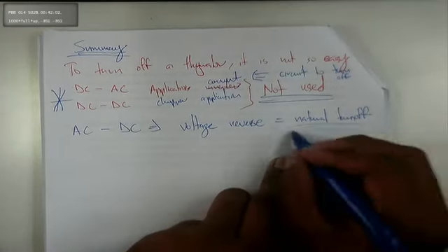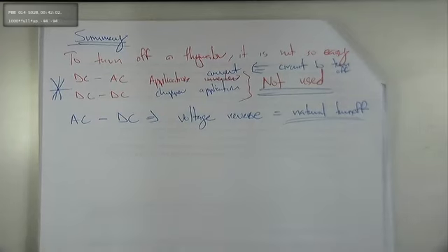Okay, you know what natural turn off means, yes? Because we have AC, we automatically go to the negative region. So we are supplying negative to the thyristor in the negative cycle. So the thyristor automatically turns off. The TQ is met, the turn off time interval. For that particular interval, we are supplying negative voltage.